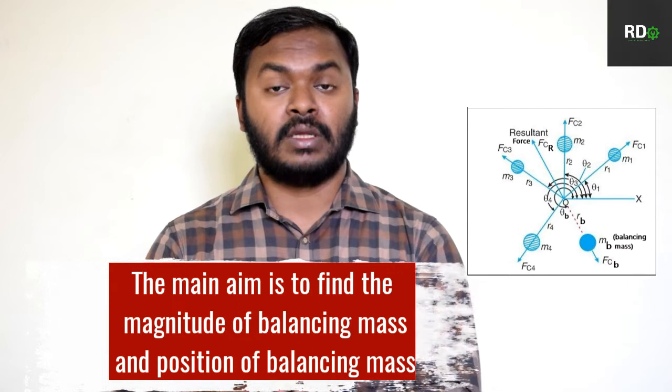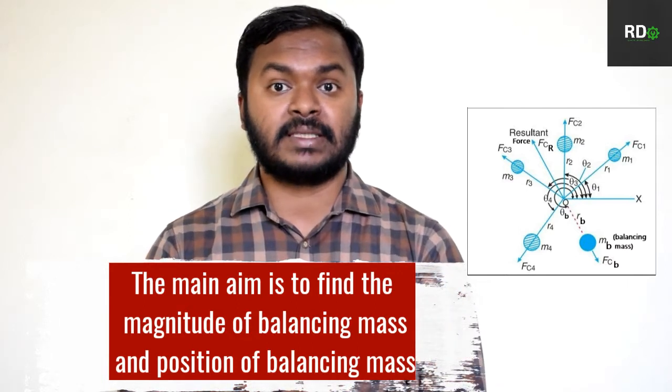So our main aim will be to find out the magnitude of the balanced mass, that is MB, and to find out the position of the balanced mass, that is theta B. We will be finding out MB and theta B, because whatever force it generates, this balanced mass will neutralize the unbalanced resultant force FCR in the system. Let's see how we do it.